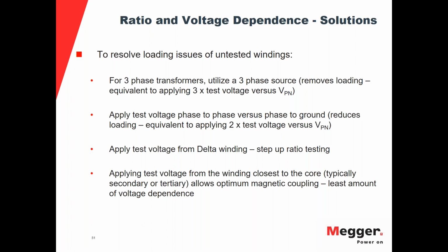I'm sorry, a unit with a neutral configuration, such as a Y with a neutral, you can do phase to ground if you wanted to, but you can also do phase to phase. And if you have a Y transformer that doesn't have an exposed neutral, then obviously phase to neutral or phase to ground either wouldn't be an option or would not be the recommended option. You would want to do a phase to phase test, and we'll see some results here in a minute and see how that goes.